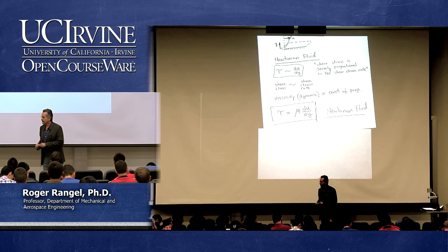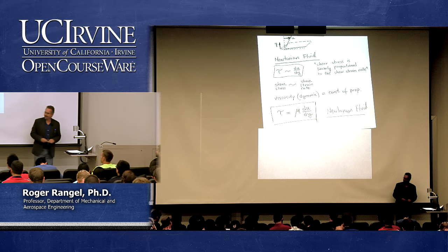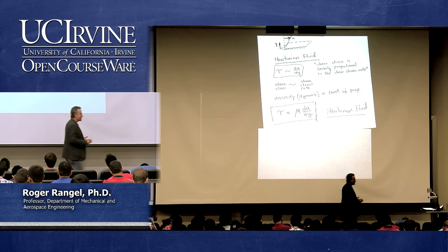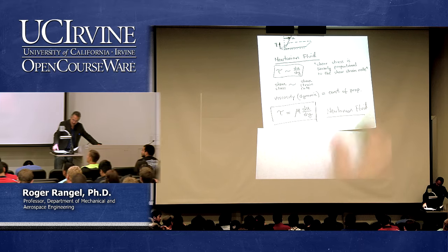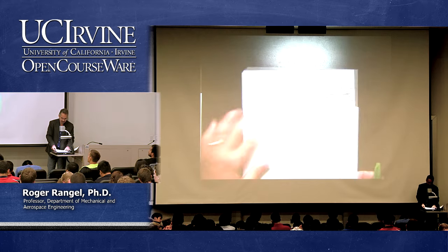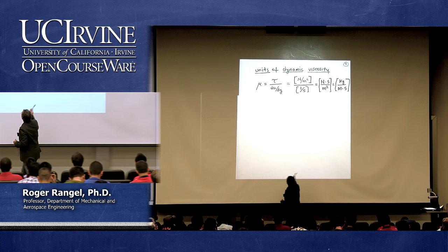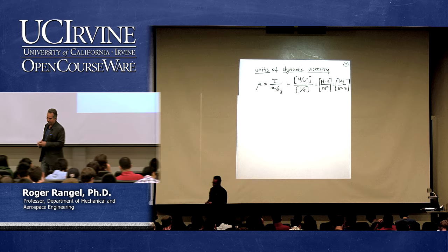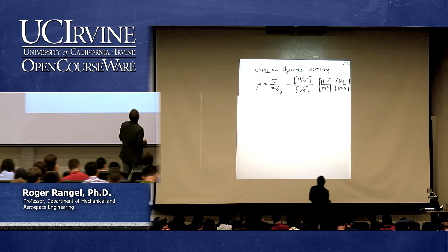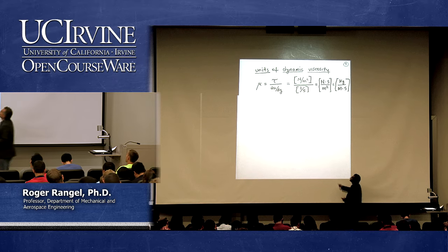It'll get more complicated. What are the units of this viscosity? You can bring Pascal. You're not going to bring your friend Pascal in now. What are the units of viscosity? Well, from that relationship, I can simply say, right, viscosity is the shear stress divided by the shear strain rate. The shear stress is newtons per meter square, which of course is Pascal. Well, I'm not using it here. Newtons over meter squared divided by the shear strain rate, which is 1 over second. Simplify everything.